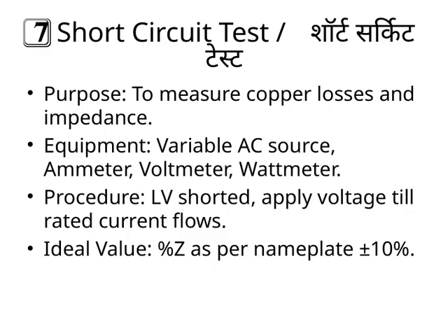Now, for the equipment you'll need. A variable AC source that allows us to adjust the voltage, along with an ammeter to measure current, a voltmeter for voltage readings, and a wattmeter to measure power consumption. These instruments are essential for accurate measurements during the test.